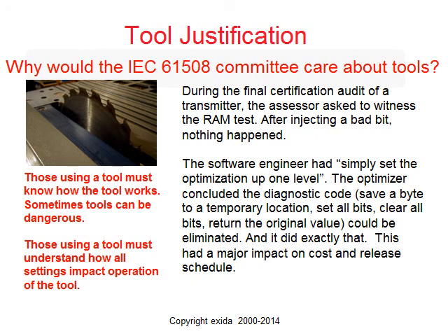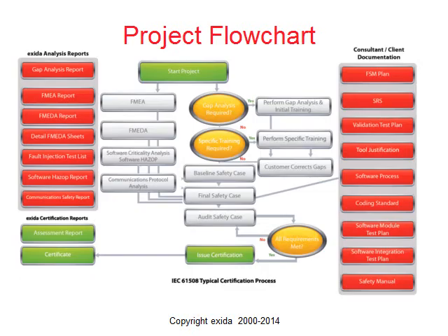It's a case of there are real faults and real problems that happen in equipment. If you're going to be using these in safety critical applications where you're claiming a lot of risk reduction, the reason you have to follow these rigorous standards is there are all these things that can go wrong. 61508 doesn't do a perfect job, but it does a pretty exhaustive job of identifying procedures and processes to minimize those systematic faults.